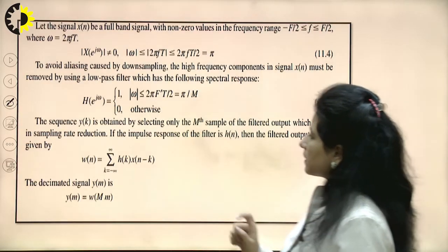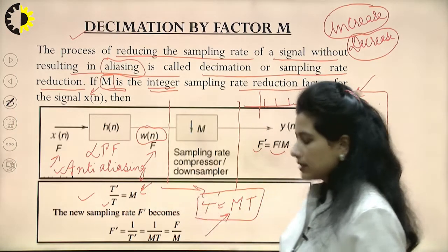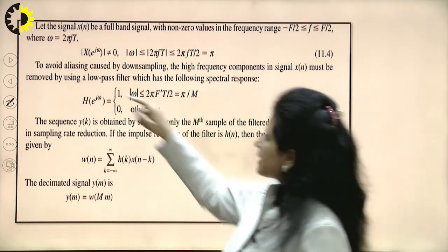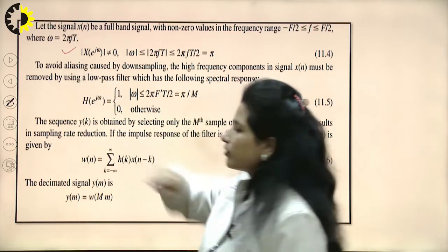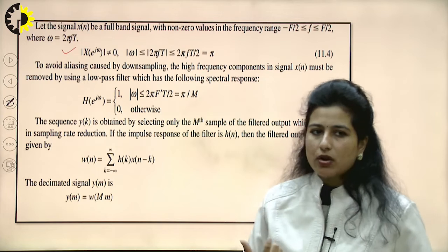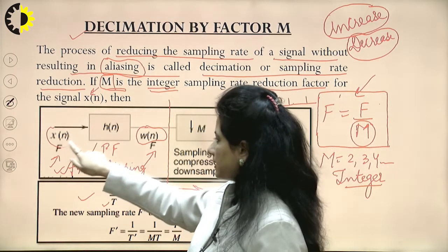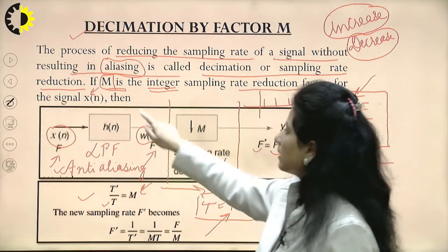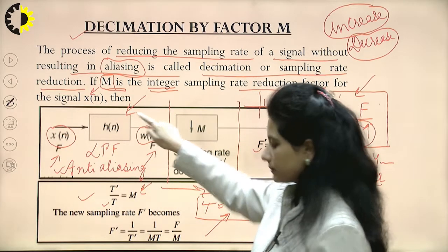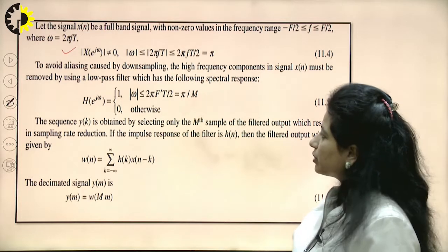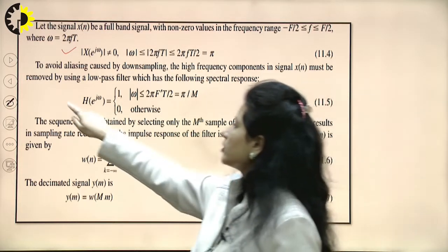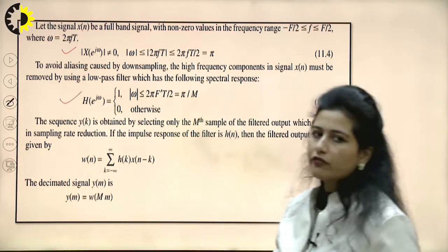So what this block diagram is doing, stage by stage: I take any signal and its Fourier transform to see the spectra of that input signal, corresponding to this x[n]. Two things are being done. One is the filter. What should be the quality of this filter? The response should look like this, H of omega.